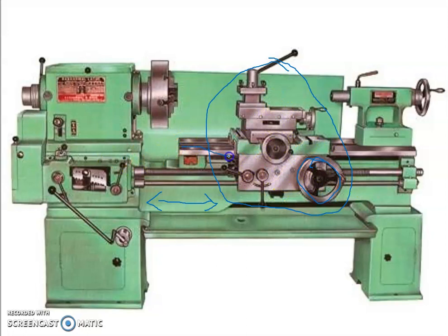For that we require guide ways. We can see this is the guide way for the carriage assembly. So on this guide way, the carriage assembly can move to the left side and right side when you rotate this hand wheel clockwise and anti-clockwise. And there is a cross slide also, sub parts, and the tool post is also mounted on the carriage assembly. So the main function of the carriage assembly is that it can control the cutting process. I told you we can cut the raw material by using the lathe. That cutting process can be controlled by using this carriage assembly or the carriage.